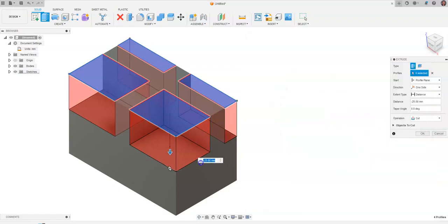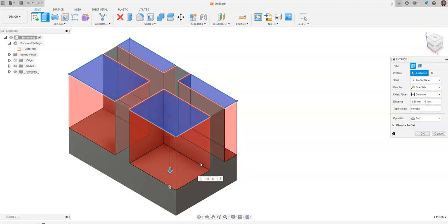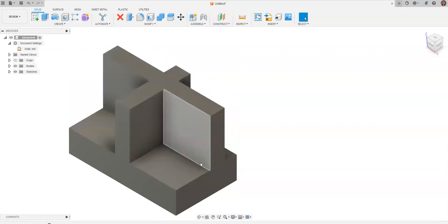Now in Fusion, one of the things I can do is hit minus for negative and start some parentheses and go 56 minus 18 and close my parentheses, and look what it did. I can just throw that math in there. So if you have a lot of significant digits and decimal places, you can throw those in there automatically, and Fusion will do that math for you. So now we're going to go ahead and hit enter.